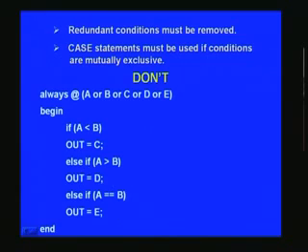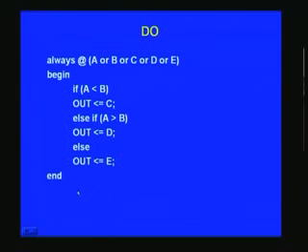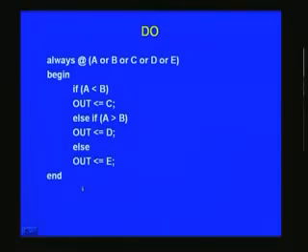So now, is there any other possibility? The solution is simple, and you can dispense with one of the muxes. After A equal to B, D is assigned, 2 muxes already present in service, and now we know that when we come to this step, it is already A equal to B. So instead of putting else if, you just put else, and then E can be straight away assigned here. By doing so, notice that else if combined with else both means a single mux only, as we have seen earlier also, and that's how we save one mux and thereby improve the speed of operation.